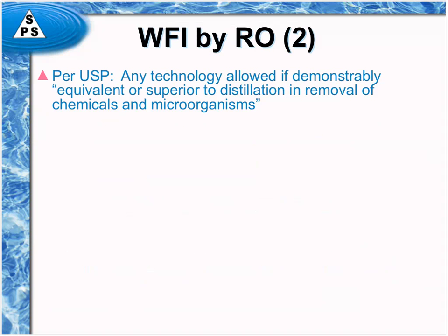Now, if you read USP, in the preamble to the WFI monograph, it basically says, and this is a paraphrase, that any technology is allowed to produce WFI as long as it is equivalent or superior to distillation in the removal of chemicals and microorganisms.